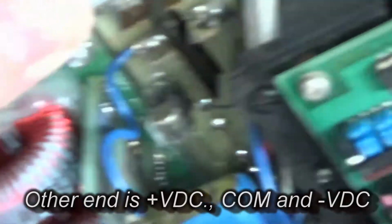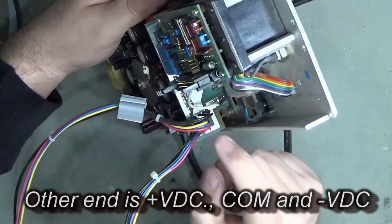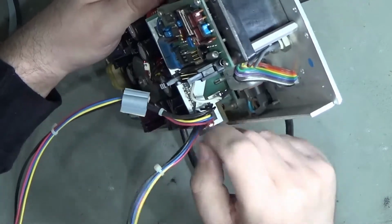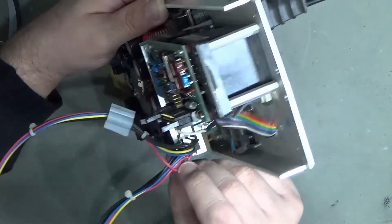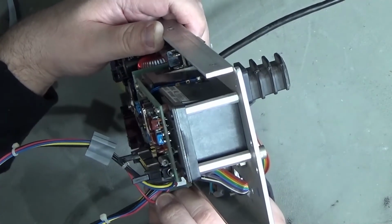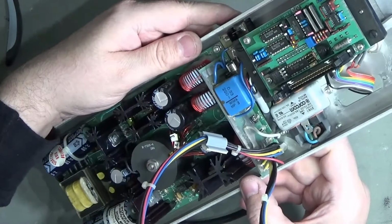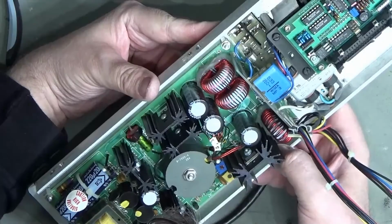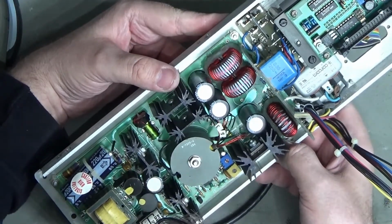I've got coming from the other end, so the blacks all go to the common, which obviously makes sense. The reds go to the plus 5 volt, the yellows go to plus V, and the blues go to minus volt DC. Again, no indication what that voltage is meant to be.